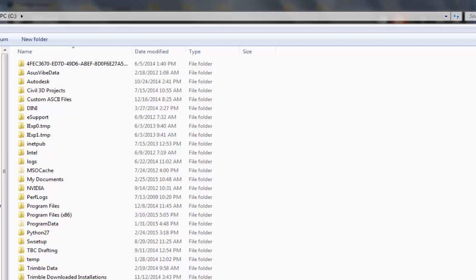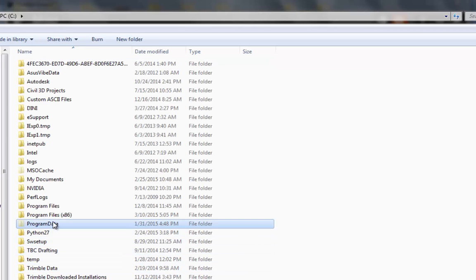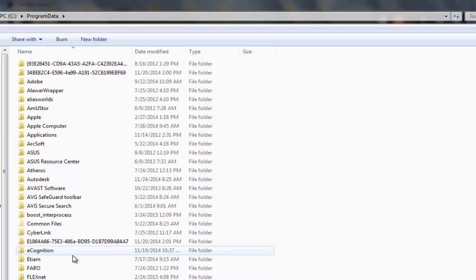Also, what I can do with that TTM file, and maybe it would be more advantageous on the road side of this thing, is let's say Brian exports out a corridor for me, and when he exports out a corridor, it's designed to finish surface, right? Well, let's say I need to stake subgrade or whatever. I can still stake this finished grade corridor, centerline, station, and offset, but I can load a TTM surface of subgrade, and I can have it give me my cuts or fill to subgrade, but reference my finished grade for my station and offset, so I have some flexibility there.